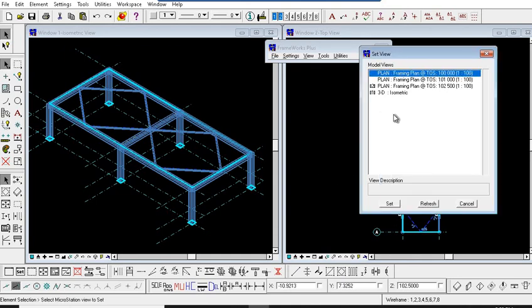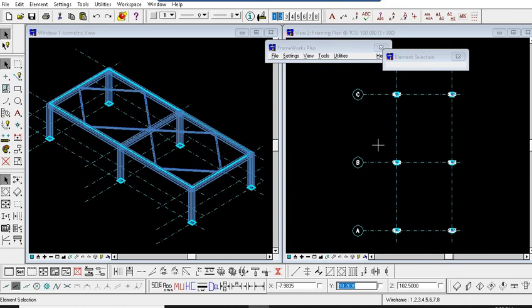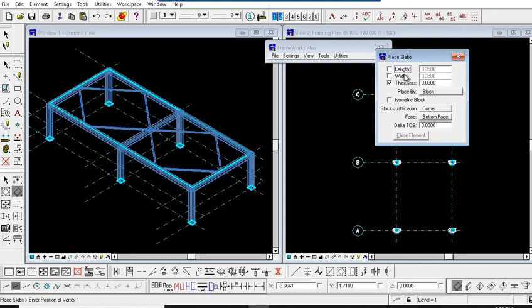I'm just going to the 100 level. I am going to place the foundation here. First, I place the footing here. Footing will be 2.5 by 2.5 meter by 0.5 thickness, center. I placed it. Then I'm going to place a pedestal.